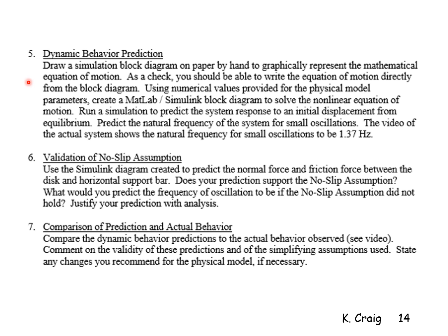As a check, you should be able to write the equation of motion directly from the block diagram. Once you have the equation of motion, in this case one nonlinear ordinary differential equation, the question then is, does the simulation diagram represent that equation of motion? That is a question you can always answer, because a check on your simulation diagram is to write the equation of motion from the simulation diagram.